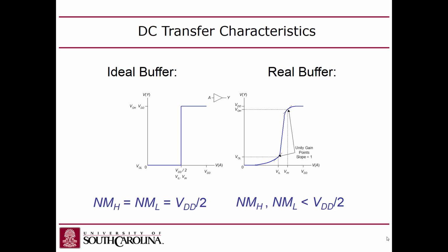Once you get beyond that, the output voltage changes. It starts going up much faster until it eventually levels out, at which point that's the V input high voltage, right? Once you hit the V input high voltage, the response becomes the output high. Sorry, I kind of boofed that explanation.